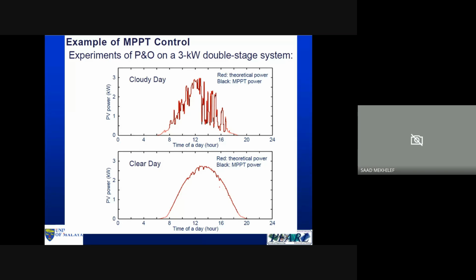For example, you may have sunlight which starts from 7 to 6, but the sun hours is only 6 hours. Maybe it's from 9 o'clock to maybe 4 p.m. only. So this is called sun hours. And these sun hours change in winter and summer. In summer, we will have more sun hours, but in winter, the sun hours become less.